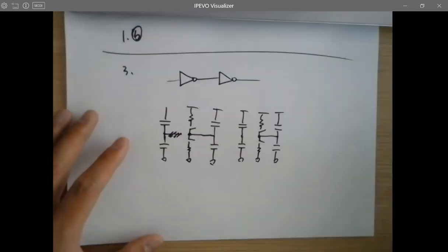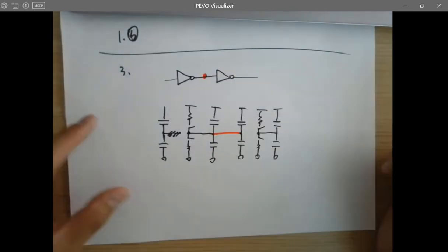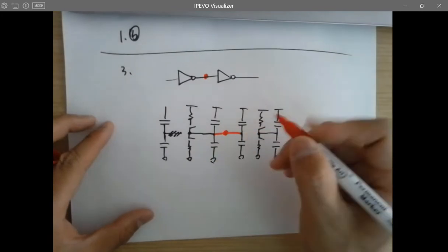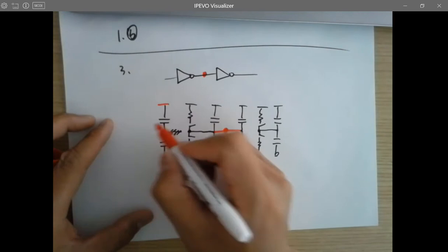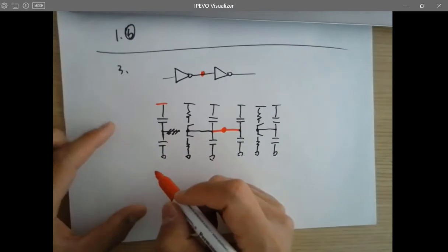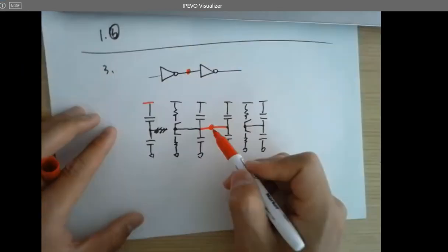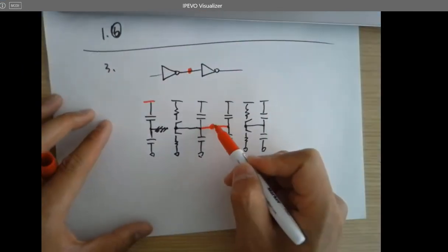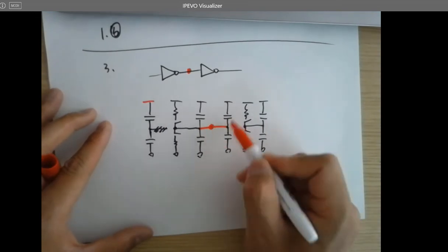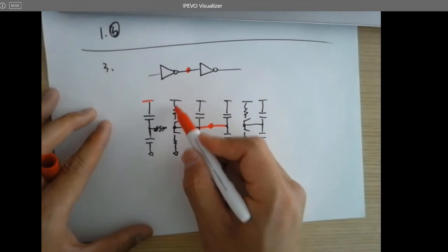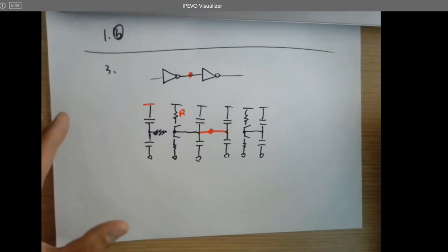Do you want to connect them together? Yes, because that's a connection here. Okay, so that's the output. So this input capacitor here is what? If you want to label it, just label it. If you don't want to, that's fine, because you're only looking at this point. So all the capacitors involved in the time delay at this point will be these 4, and the resistors are this one or this one, depending on whether you are looking at THL or TLH.